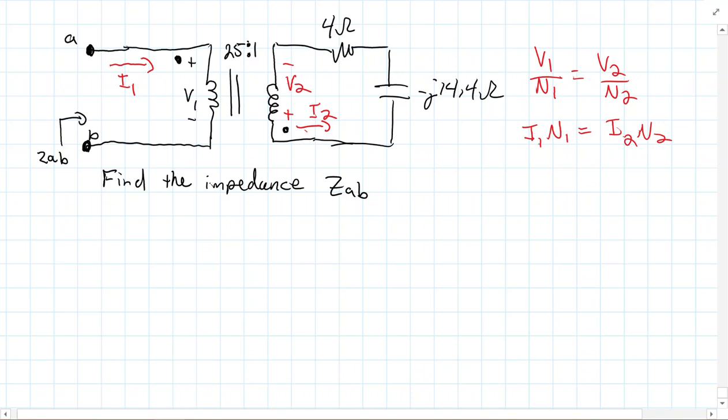The difference is, if you look online or in your book, the difference is that there's going to be negatives floating around in these equations. And that's why I just like say, well, remember one set of equations. You don't have to worry about negatives, and just always set it up like this so that you have the pluses for both V1 and V2 at the dot. I1 enters the dot. I2 leaves the dot. Alright, so we've got it set up now.